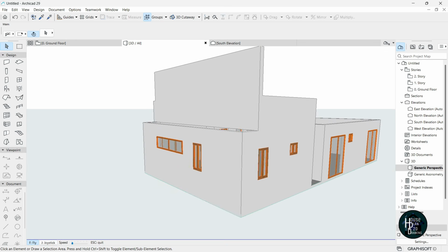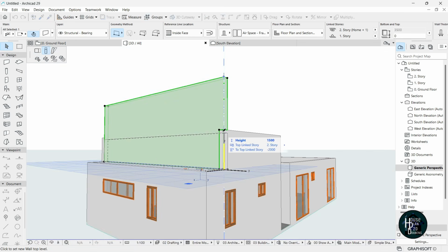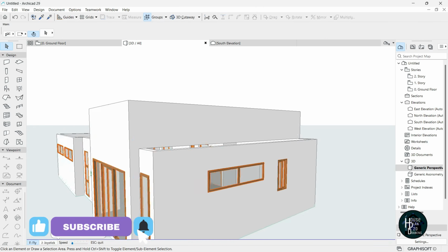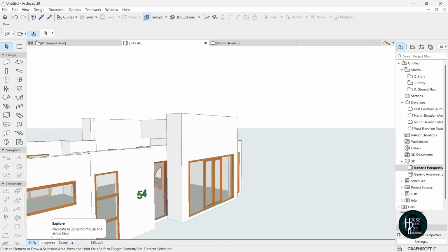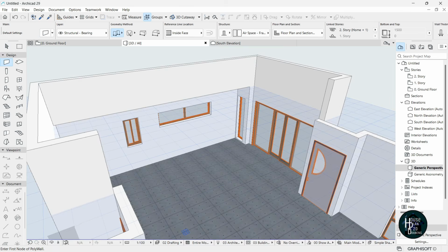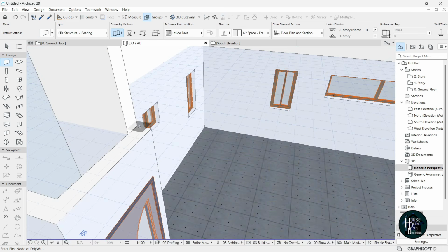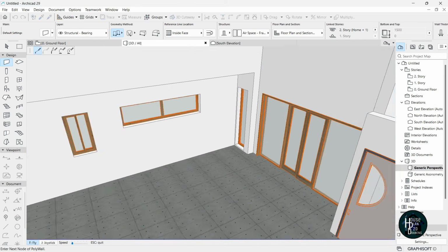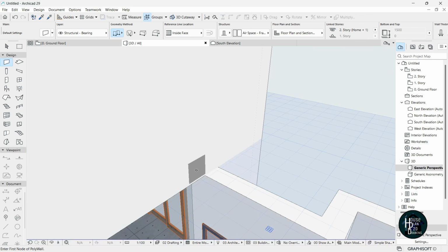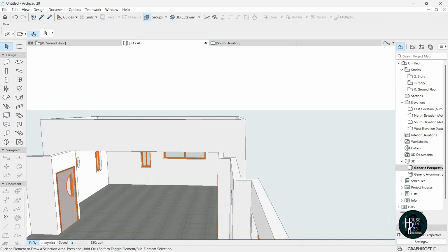Okay, now the next thing I want you to do is click on the node here, and then select the stretch height, and then select like so. Press escape, and that should give us a closed fit, as you can see. Alright, so you want to do the same thing for this other side too. So you just want to hold Alt, select this, and then do the same thing I did. Select this, press escape, and now you should have something closed off like that.